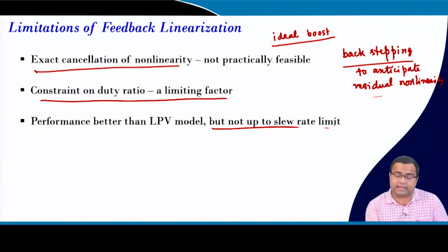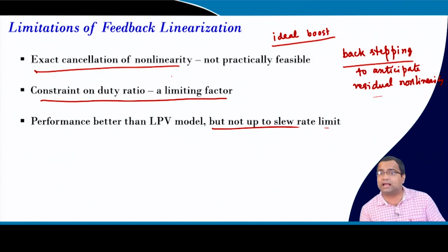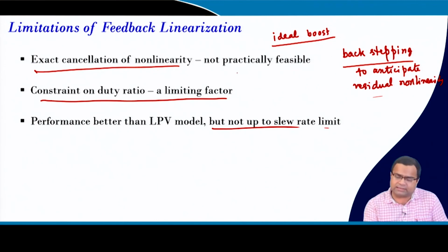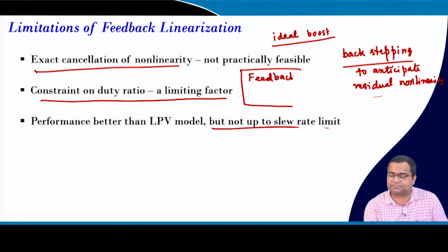Another thing I can say, cancelling the nonlinearity may not be a good idea; rather, keeping the nonlinear model and taking advantage of it may be the better idea. This method comes from the concept of feedback linearization.